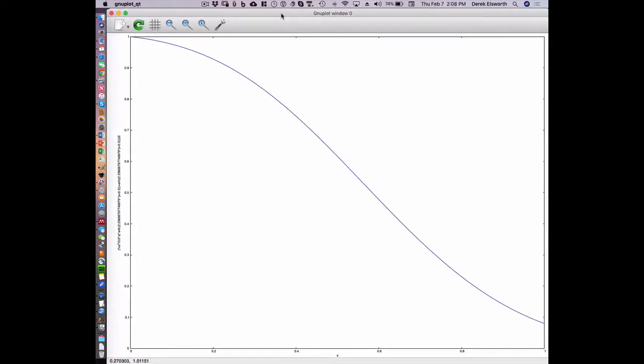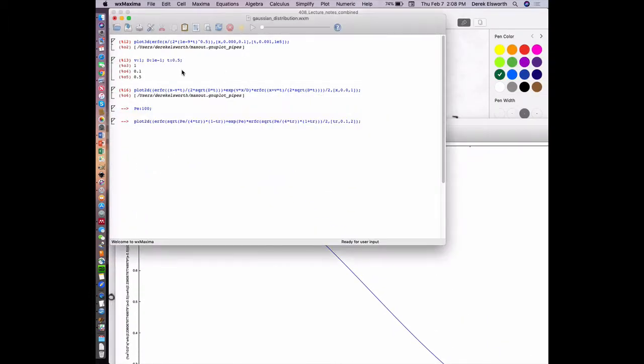Very big all of a sudden. And on the bottom we have location between upstream and downstream, and we see exactly what this plume looks like as we go through this. And so this is the plume at a snapshot in time. Upstream concentration is 1, C over C0 is 1, and the downstream concentration is beginning to build at the end of the sample, and it's some distribution over the length of it. So I suppose what we could do is take the velocity and make it bigger. We could do all kinds of things. We could make the velocity 100, and if we did that, you could guess what might happen.